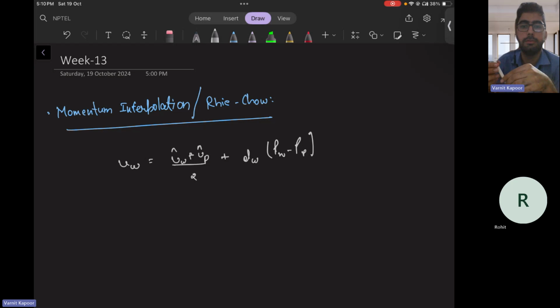So u_e and u_w are functions of adjacent pressure values, and the continuity equation does not support pressure checkerboarding. That's good news, because we need to avoid checkerboarding. Then the u_e, u_P, and u_w momentum equations are still functions of non-contiguous pressure values.